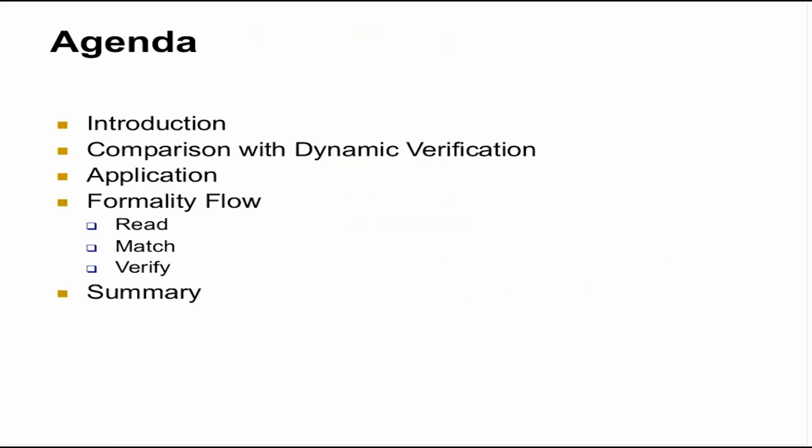I'll introduce the topic and then we will compare it with the regular dynamic verification, that is the stimulus based verification, and static timing analysis both. We'll see where equivalence checking lies in the ASIC design flow, how it is useful, and what is its uniqueness. We will look at the applications, where and in what places we can apply it.